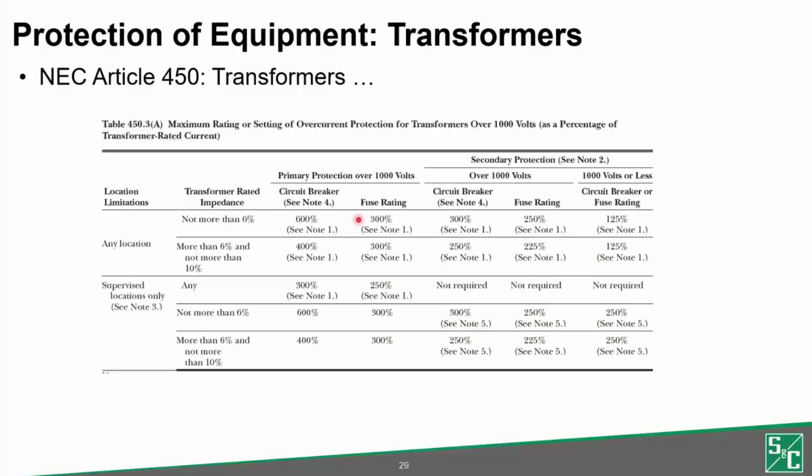It's 200 amps. So medium voltage fuses operate at double their rating. So if you needed to trip at 200 amps and you put a circuit breaker and typed in 200 amps, that would be 600% of the transformer you're trying to protect. Again, if you want the same fuse, you have to get half the rating, and that's why that is 300 versus 600. Just a little side note there.